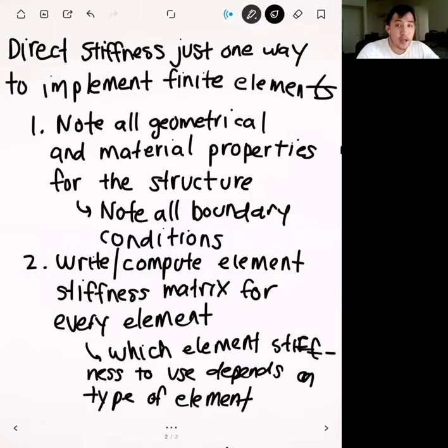And so if you're doing a truss problem, a beam problem, or a frame problem, all of these have their unique element stiffness matrices. And for trusses and frames, we did a lot of practice problems in 2 dimensions too. So we had to do the transformation between the local coordinate system and the stationary one.